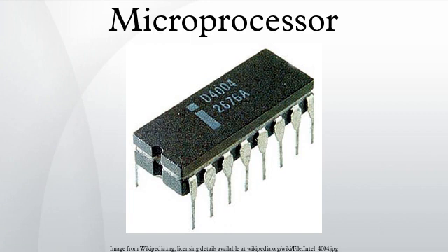The third-generation chip, the NS32532, was different. It had about double the performance of the MC68030, which was released around the same time. The appearance of RISC processors like the AM29000 and MC88000 influenced the architecture of the final core, the NS32764. Technically advanced, with a superscalar RISC core, 64-bit bus, and internally overclocked, it could still execute Series 32000 instructions through real-time translation.